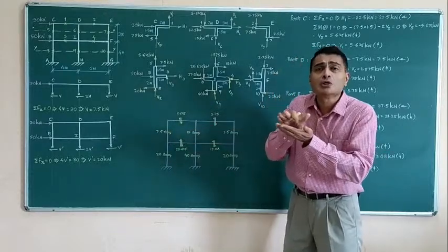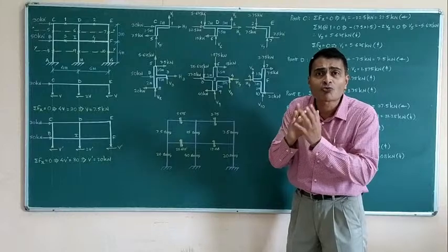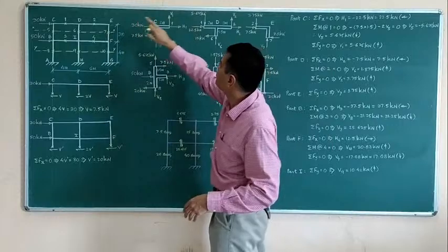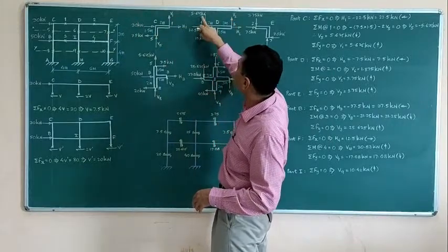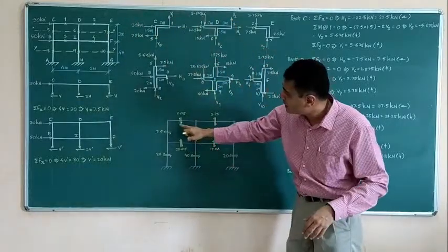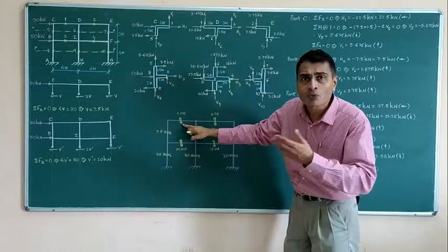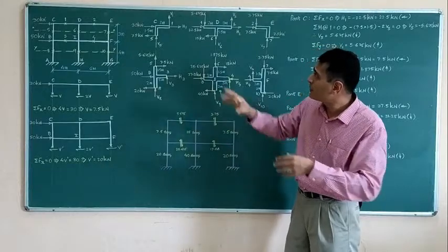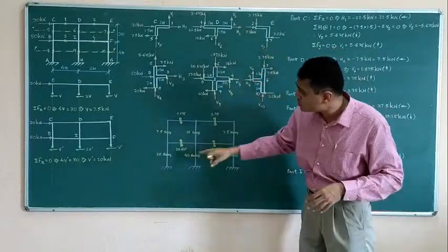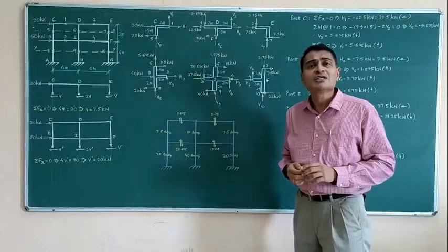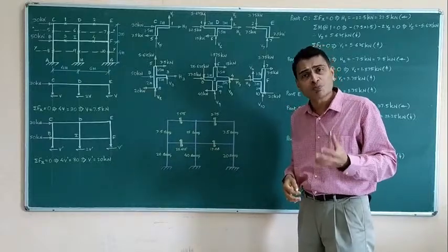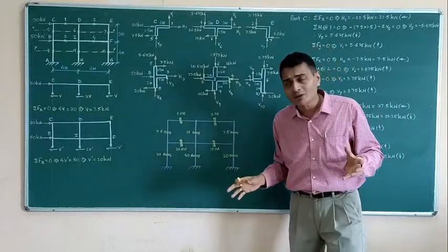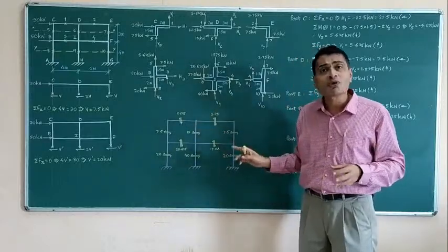This is the typical notation or way of representing shear force. Similarly, here if you observe, for the left portion it is upwards, for the right portion it is downwards. So I have shown above and below, upwards and downwards, and I have written 5.625. Likewise, I have shown the column shear as well as beam shear in each column and beam at the point of contraflexure. This is my first step.